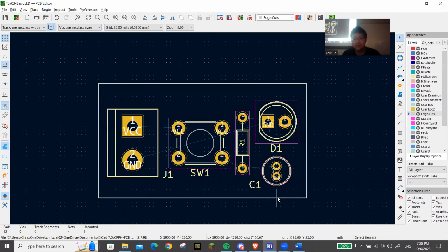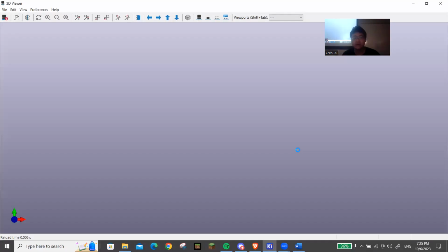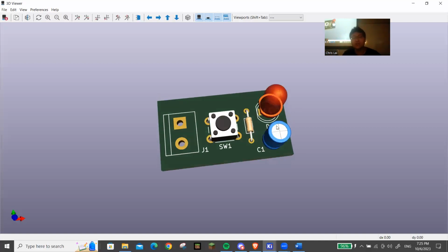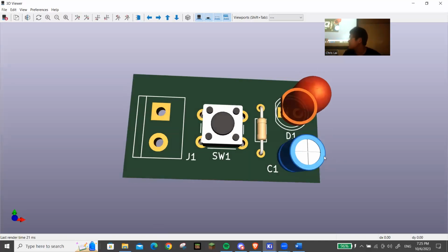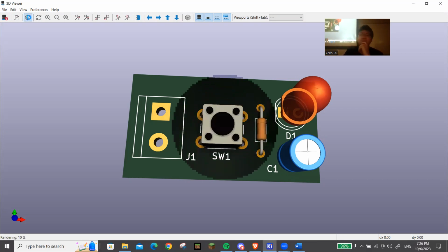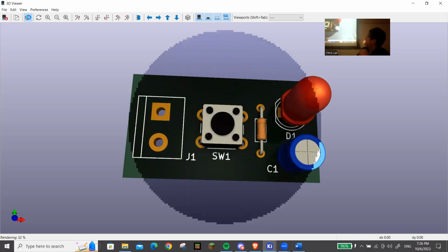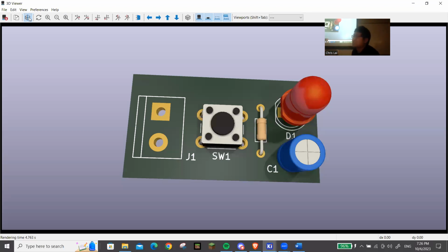All right. So once you have finished edge cuts, again, you can press Alt-3. Alt-3 is the command to see a 3D representation of your PCB. The cool part about this is you can also make a rendering, and you can use ray tracing here. There's a button on top to make a really nice view of your PCB, and it just generates it all. It's pretty cool. There's shadows and everything. It's awesome.